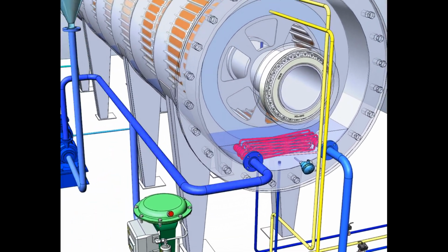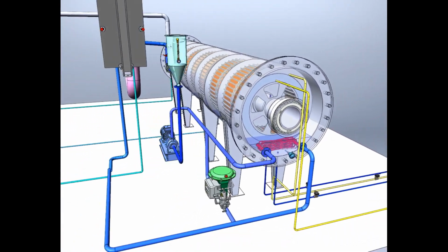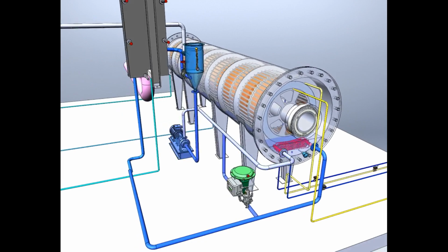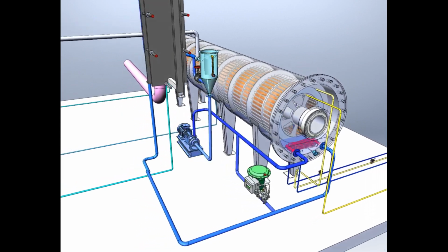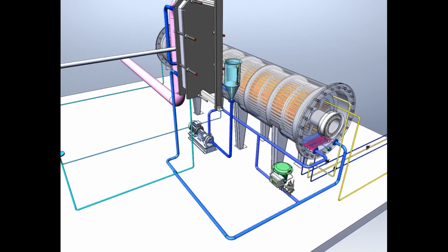The cooled water is sent to a plate heat exchanger to condense the steam compressed in the vacuum pump. The regulation of steam generation in the apparatus is carried out by changing the flow rate of the coolant by means of bypassing the boiler tubes.